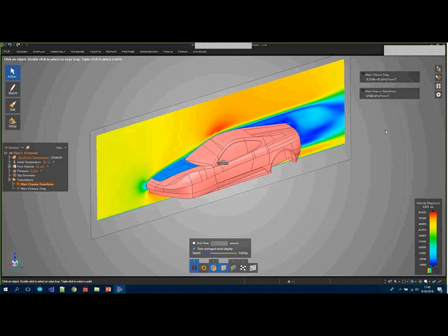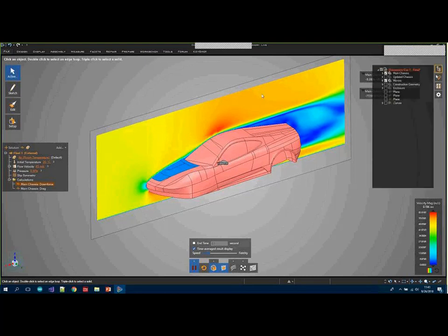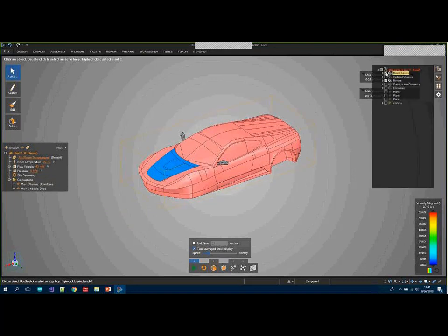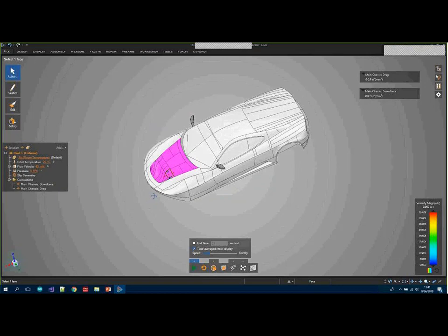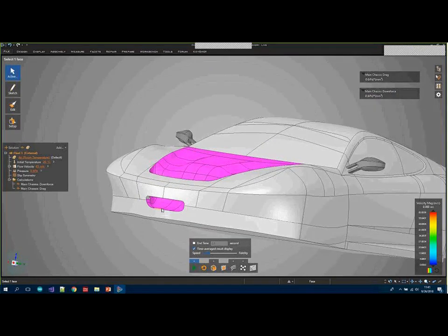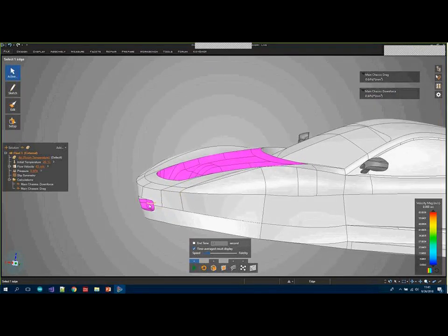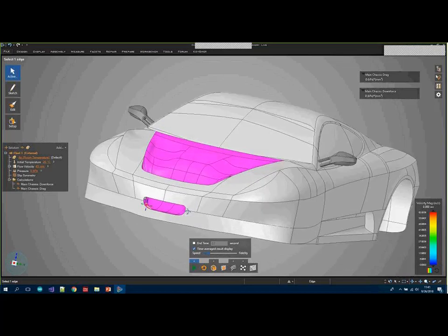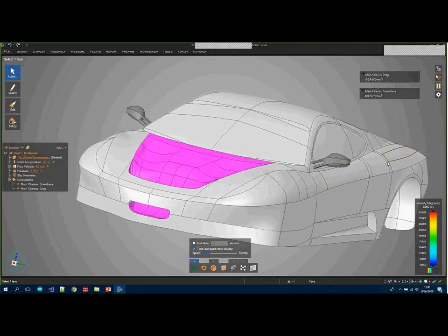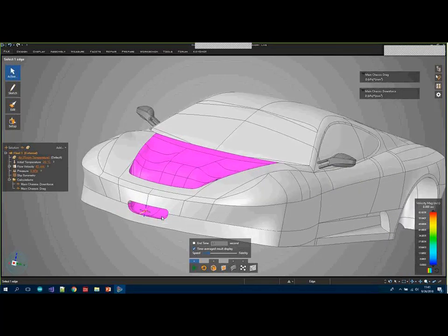Now, for the next example, or the updated model, here's what happened there. This was the classic design. The updated design has what's called an S-duct. Now, this S-duct is intended and designed to allow airflow to come in through the front here, where the grill area is. In these cars, it's a rear engine or mid-engine design, so radiators tend to be in the back. The airflow into the radiator would come in, through, there's usually a duct over here for the intercoolers. And then there's some extra ducts around here to move the air around into the brakes and so on.